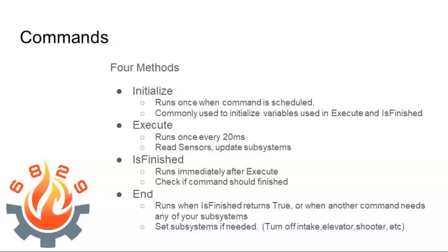If you don't, it just calls execute and is finished, and WPILib goes to the next command. It comes back to you again and calls execute and is finished. Are you at 5 feet? No. It goes around, comes back to you. Execute. Again, I'm still applying power to the drivetrain. Is finished. Oh, I've driven 5 feet? Yes. It then calls your end immediately, and at that point your command goes away, right? You're now finished, right?